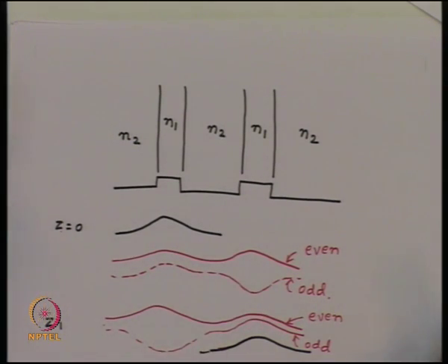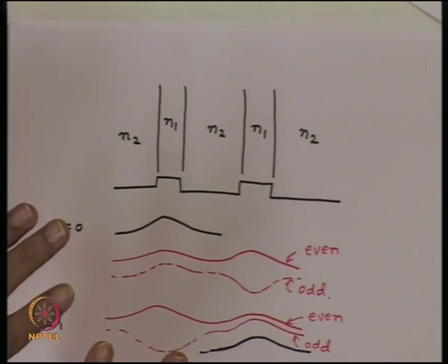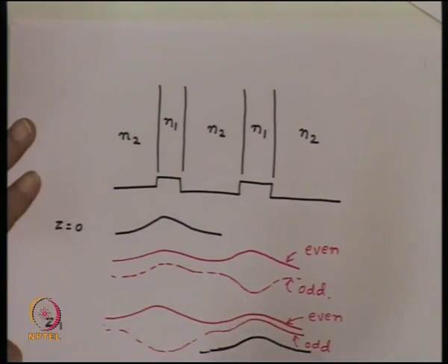Or in other words, what we are seeing is, if we bring these two channel waveguides together, not only a small power will be tapped from this waveguide to this waveguide. In fact, after a certain distance, the entire power will shift to a second waveguide. So through the evanescent field, the coupling is something which can take away the entire power from the original waveguiding structure.